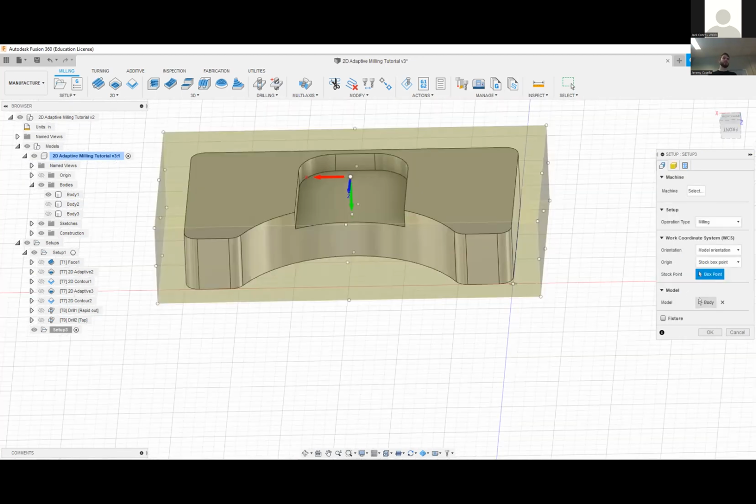Can anyone guess what the first thing I'm going to do for this block once I flip it over is? 0, right? And then the first tool path I'm going to use to cut is going to be face. And then I'll get rid of the weird geometry in the center with an adaptive, right? And I'll finish it with, someone said it, contour.